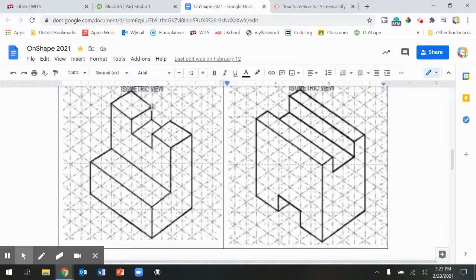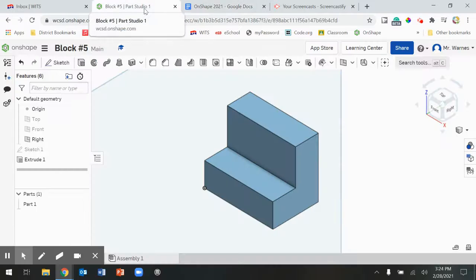Okay, and to do this, we're going to do this right from the top view. Okay. And what we're going to do is just draw 2 lines, and it's going to create 3 new faces up here, and we're going to remove this face right here. Not totally remove it, but we're going to extrude it down 1/4 of an inch, so down 0.25.